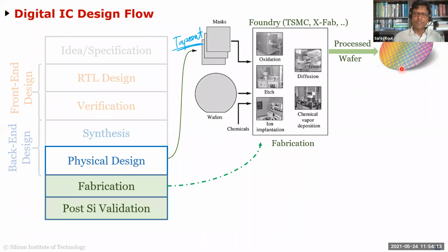But before you do this, a lot of the companies where testing is very critical and expensive will do what's called wafer probe testing. Before they dice it, they will actually go into a wafer probe tester, and they have very fine probe tips, like 100 micron tips. They will probe in and do the testing. And I keep saying dies, right?